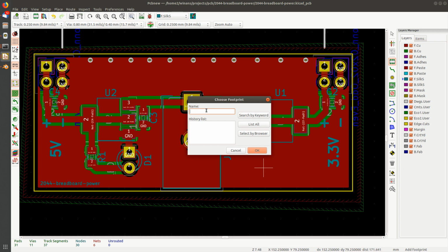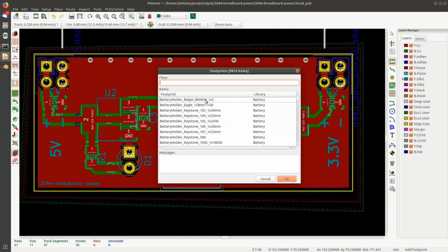I happen to know there's an open source hardware option. I list everything, okay? OSHW. And they give you different sizes. So this one is 7.3 millimeters and so on. We don't have a lot of space. And if you're going to draw it in the copper or on the silk screen, they give you different versions. Right now I've selected the silk. I want to draw this with the silk. And you got big ones and little ones.